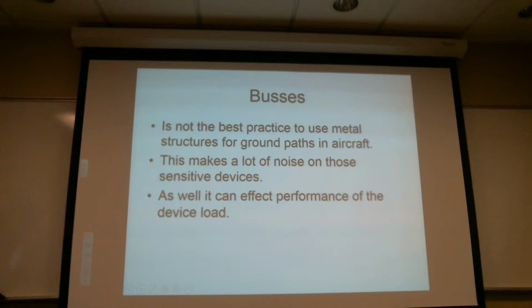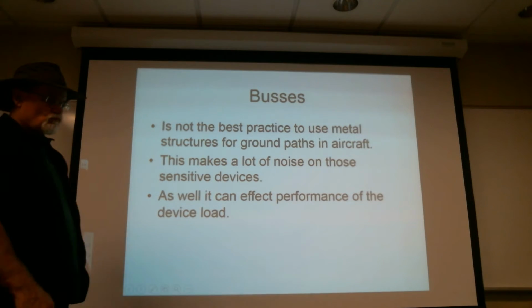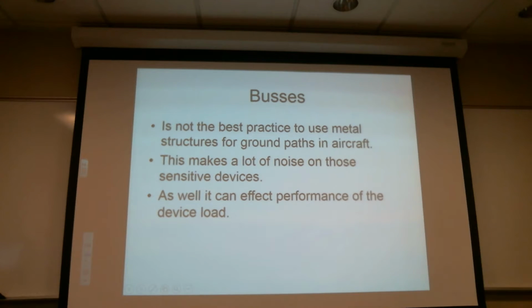So for example, BMW 329s had an electronic ignition circuit. The power that went to the electronic ignition circuit was fairly fancy, and it was a simple little thing, but the grounding path for it came back to the main fuse panel. There was a problem in this big multi-jack connector that went to the bottom of the fuse panel, and one of the connectors for the relay for the fuel pump, ignition unit, and everything else went into this, and it wouldn't connect that well. Instead of going in the hole like that, it would go like this.